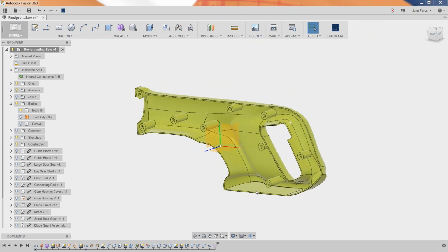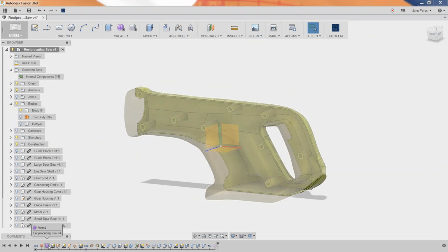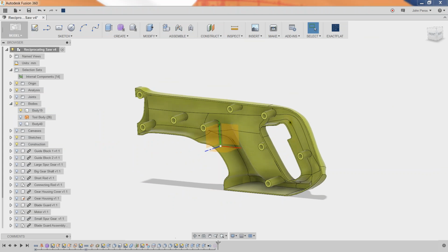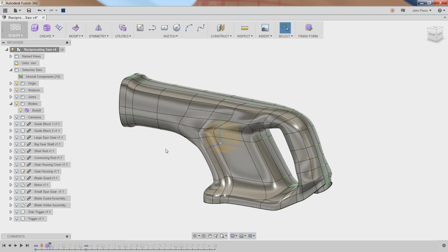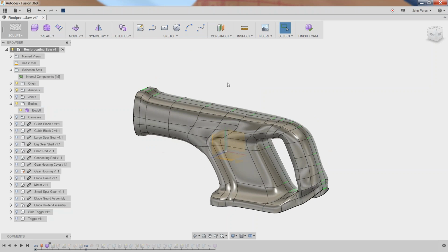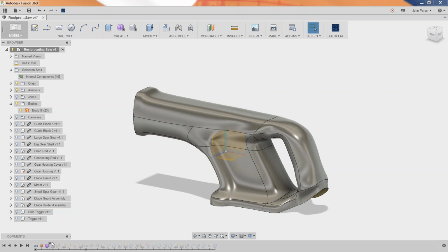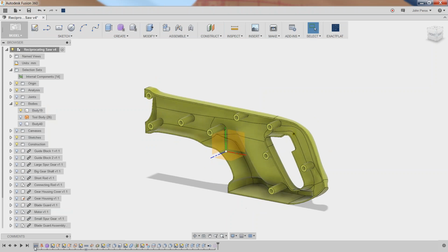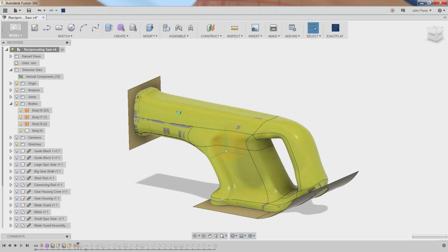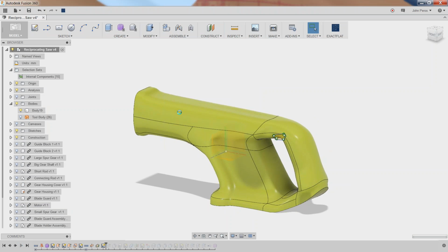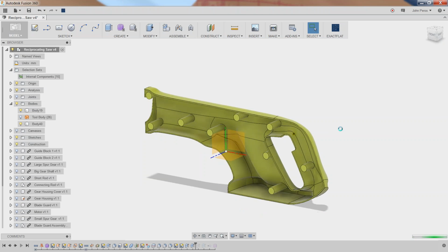So if you look at my timeline, I've got another one of those purple squares at the front, another one of those sculpt features, and if I roll back, you'll see that this whole housing was created with an initial sculpting feature. Right? So that looks great. They did the sculpt, and then they obviously put a lot of parametric stuff on top of this. And I can even play the history if you want, and you can see that the surface was here, and then it was capped and thickened and shelled and cut in half, and notches were put in it, and there's all sorts of stuff done, but it's all based on that initial sculpted surface that I did in the first place.